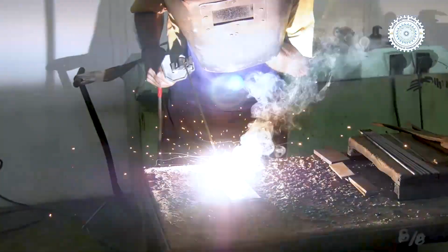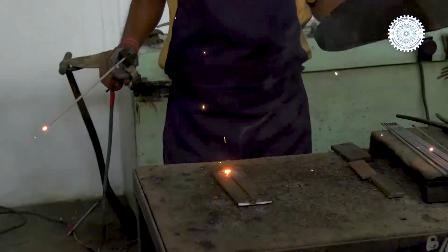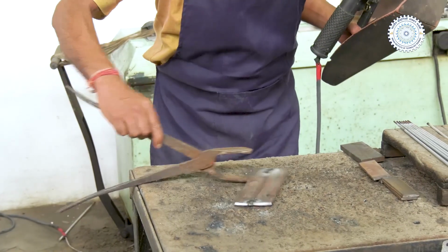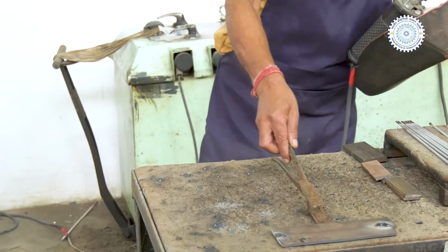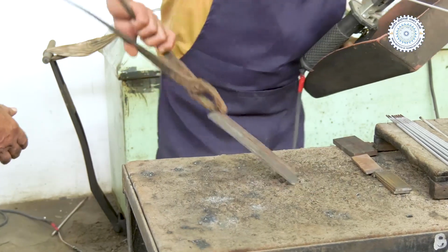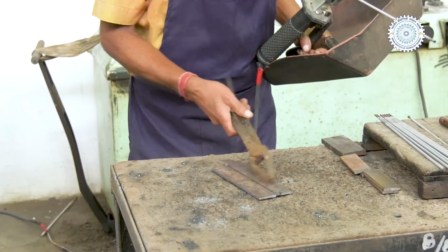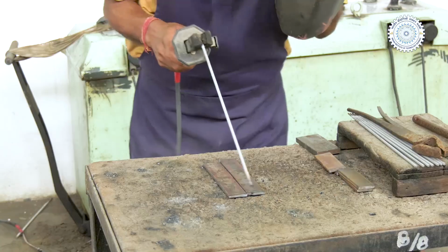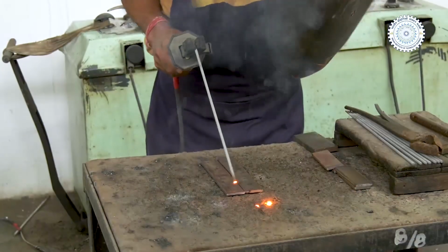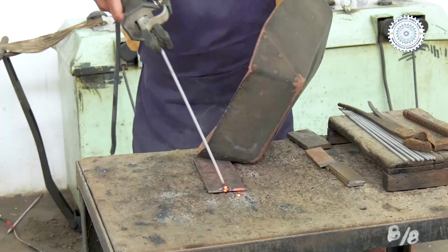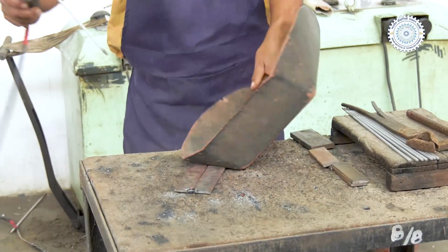So, to maintain that the plates to be joined are kept in a particular position and spacing, we do the tack welding. The tack welding is being done at the top as well as at the bottom. This will help to retain the two plates to be joined in a particular position, so that they do not go out of position. This is the tack welding on the bottom side. This is how we move the arc towards the location where heat is to be applied.